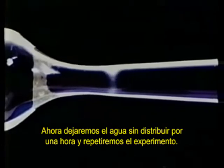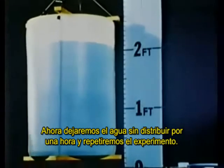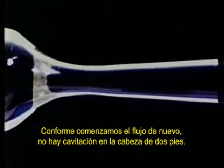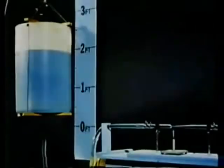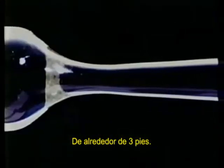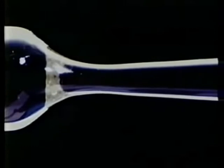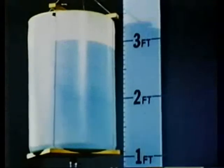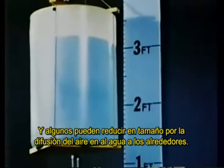We will now leave the water undisturbed for an hour, then repeat the experiment. As we start the flow again, there is no cavitation at the 2-foot head. With the settled water, a much higher head is needed for inception of cavitation, about 3 feet. During the settling period, some nuclei could rise to the surface and vent if they were very large, and some could decrease in size by diffusion of air into the surrounding water. Consequently, a greater pressure reduction was required to cause cavitation in that sample.